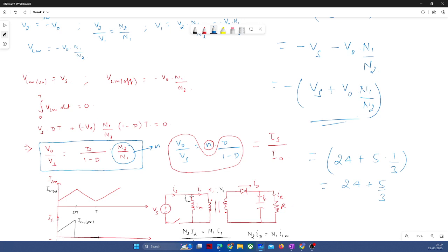Sir, we have found the voltage test across the switch, and when it is trying to switch off, a voltage spike appears across the switch, which is greater than this value. When we are switching off, the switch will see a higher voltage than this, you are telling. Yes, sir, at the moment of switch off.